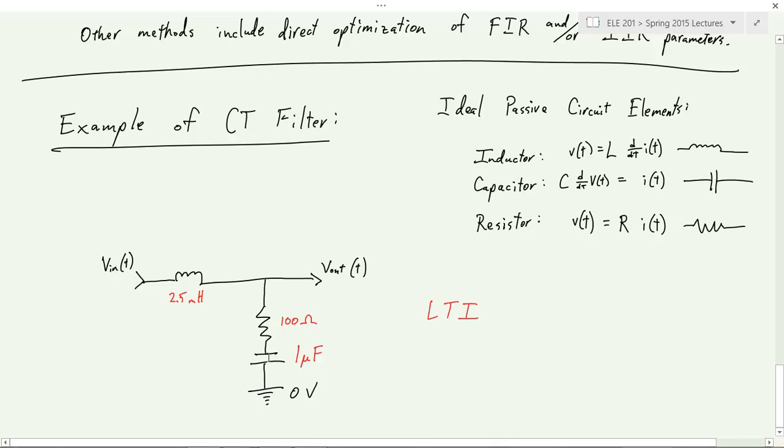Okay. The reason it behaves like it does is after a while it builds up charge, and it can no longer take any new current unless you push harder with a harder voltage. So really, it's the integral of the current that went through that tells you how much total charge there is there. And that total charge is going to cause a voltage. So that's why, if you take an integral here, you'll see the integral of the current is the voltage. Okay.